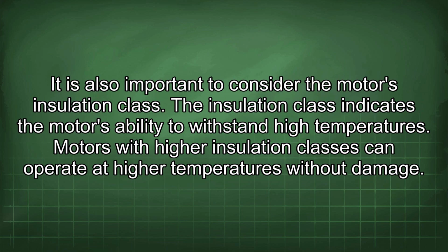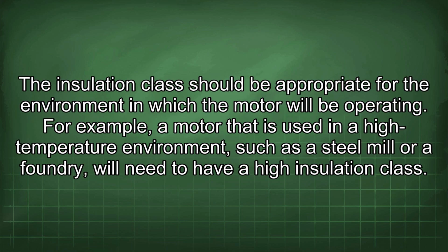It is also important to consider the motor's insulation class. The insulation class indicates the motor's ability to withstand high temperatures. Motors with higher insulation classes can operate at higher temperatures without damage. The insulation class should be appropriate for the environment in which the motor will be operating. For example, a motor that is used in a high-temperature environment, such as a steel mill or a foundry, will need to have a high insulation class.